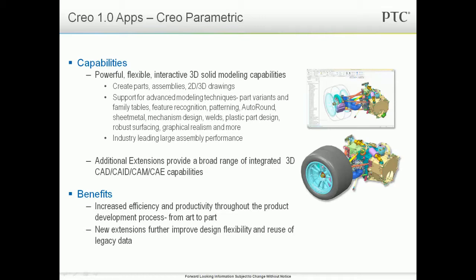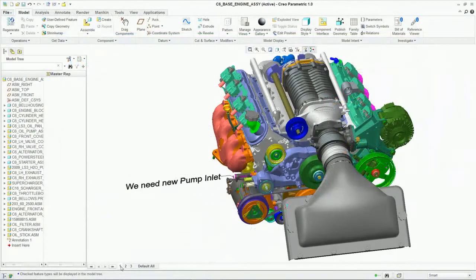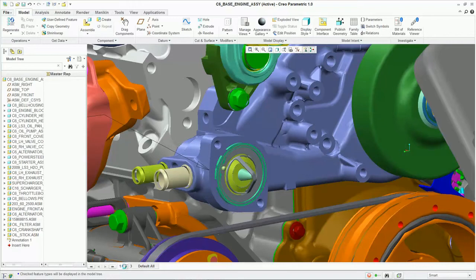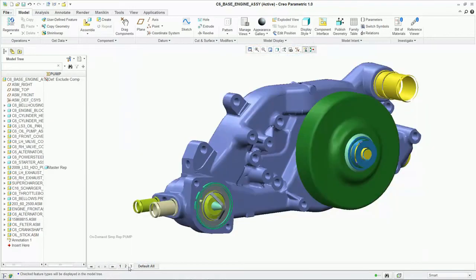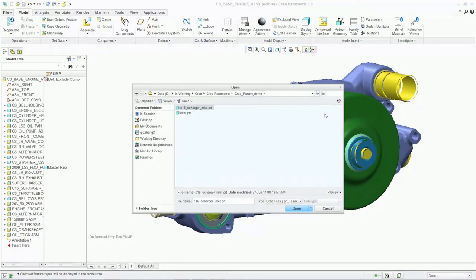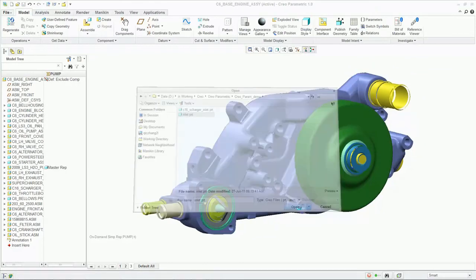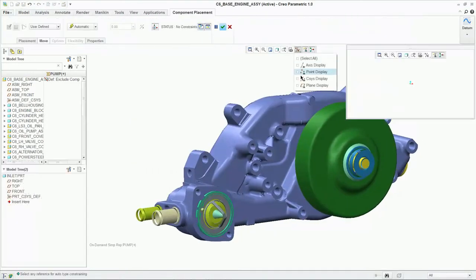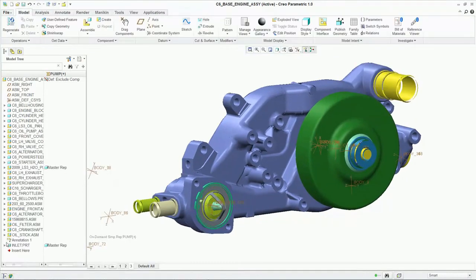From the assembly model window, we're going to take a look at some combined views which are located at the bottom of the graphics window. Here we can quickly preview and access the desired states. Now, we want to assemble a new part model in the assembly. Notice we can use the search tool to quickly find it, and simply select two coordinate systems in the part model and the assembly model to create a coincident assembly constraint.